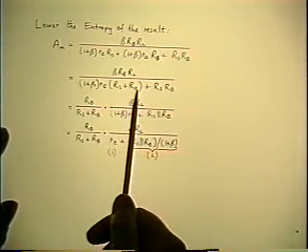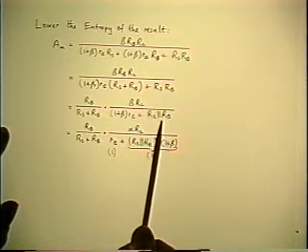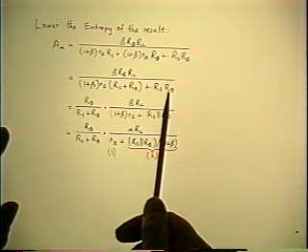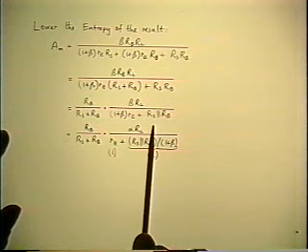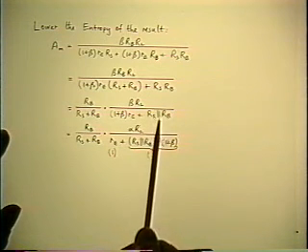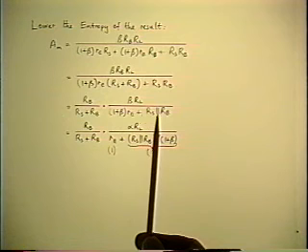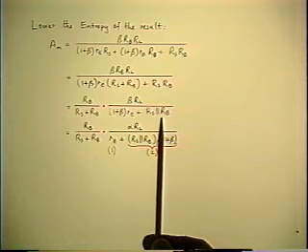Now, if I bring out the RS plus RB from the first 2 terms, then of course I have to divide it into the third term of the denominator. So I get product over sum. But that should be identified as parallel combination. So write it that way. Notice already you see an aspect of design being the reverse of analysis. You observe product over sum and you replace it by the parallel notation, which is the opposite direction from what you normally do. But this is how you get the benefit of the low entropy result. So now we have a denominator which illustrates that parallel combination.